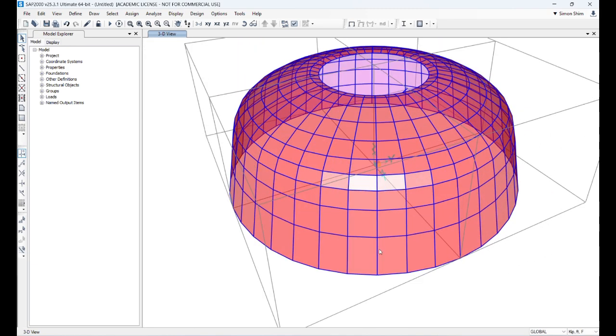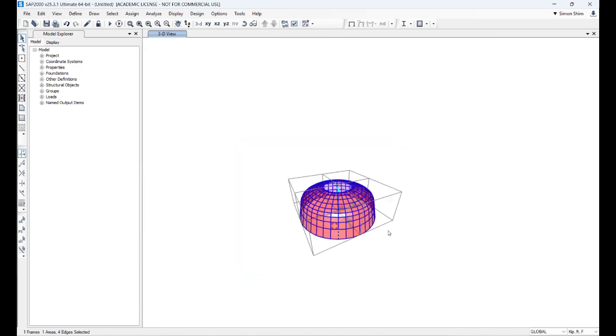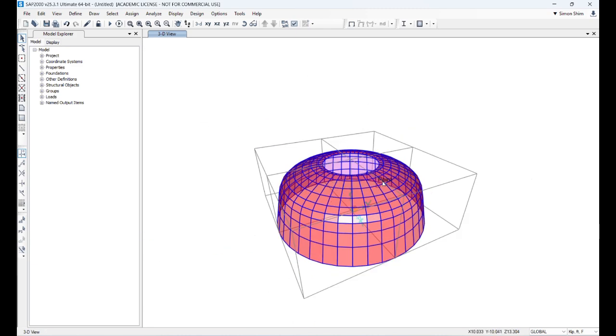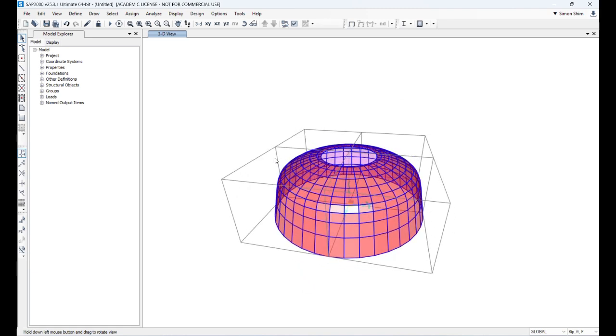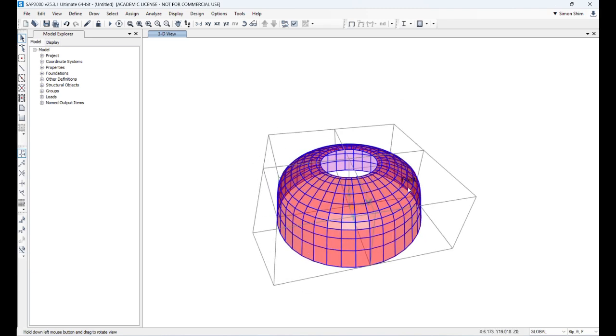So I want you to make sure that all the lines in the SAP structural model are straight lines. There is no such thing as a curved line; SAP cannot recognize it. So you need to subdivide and segment all the lines, but they should be straight lines. A curve is the same thing. There is no such curve element.